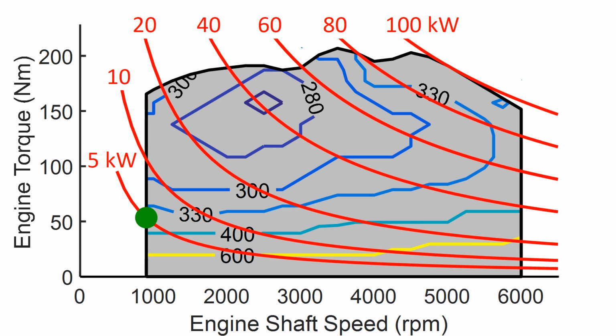If we do the same at 10 kilowatt, we get this operating point, which is at a fuel consumption of 295 grams. At 20 kilowatt, the minimum consumption is 278 grams at 1400 RPM. At 40 kilowatt, the lowest fuel consumption is at 2400 RPM. This is also the most efficient operating point of all in the whole operating range, only 260 grams per kilowatt hour. Up to this power, the specific fuel consumption at the optimal operating point has been decreasing from 350 grams at 5 kilowatt to 260 grams at 40 kilowatt.